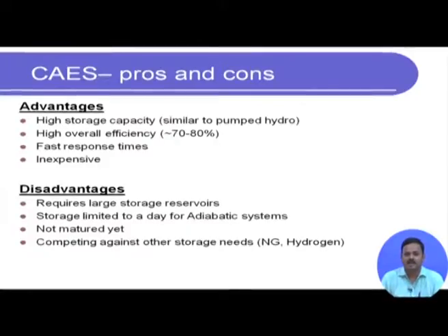Secondly, for adiabatic systems, the storage is limited. What is an adiabatic system? It is where we do not need that additional energy supply through combustion. An adiabatic system is where there is no heat loss, so the compressed air hardly loses any heat and comes out at the same temperature. But that is not possible, because first of all, in the reservoir itself there will be some heat loss to the ground, and also the regenerative heat exchanger that we use cannot hold that thermal energy for too long. By law of nature, it is going to dissipate that heat over some time.